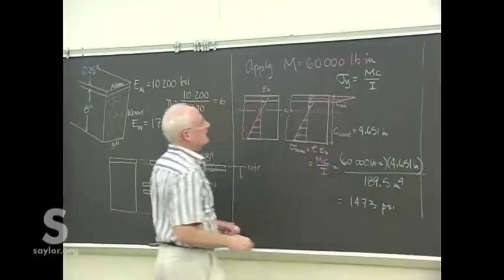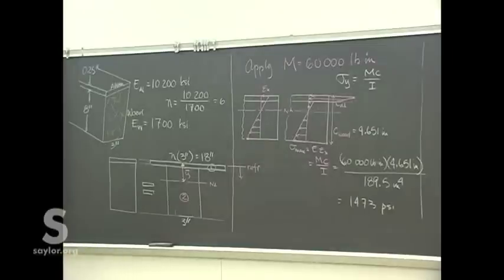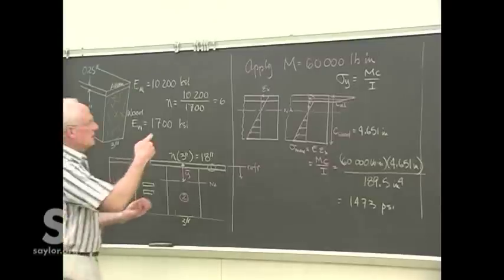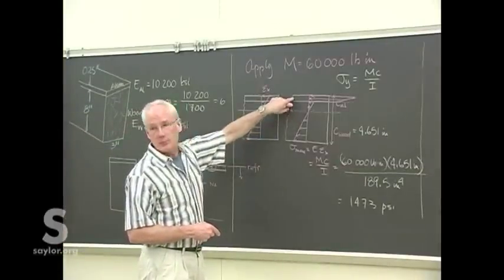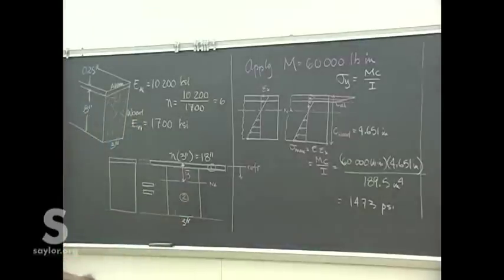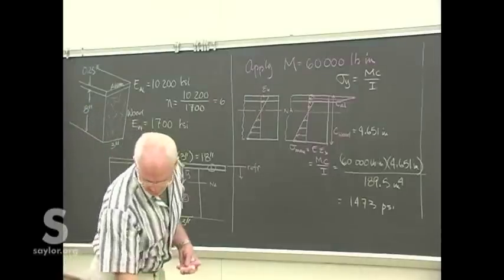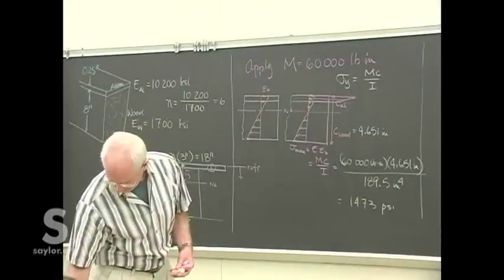Much greater compression ability of the aluminum, which is part of the reason it may have been in there. Might have been that for that load, the wood would not have been sufficiently strong, so you put in an aluminum plate across the top that absorbs a lot greater stress, and then put the wood on the rest on the bottom for perhaps aesthetic purposes or for weight purposes.